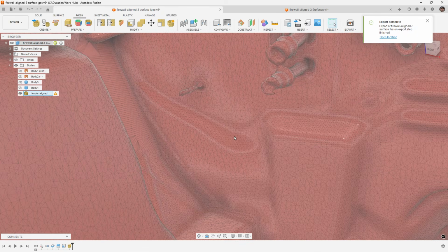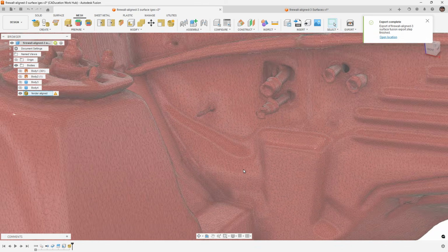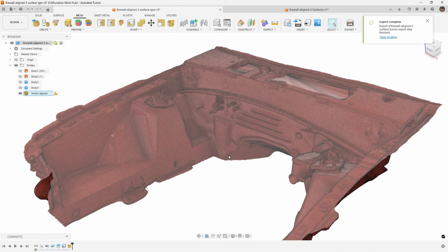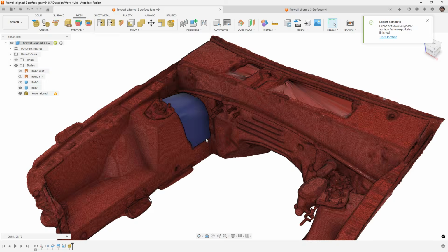So the higher quality that you can get in those areas, the better off you will be getting your parts to fit. So if you're going to scan an entire engine bay in this case, you might do a secondary scan at higher resolution and do some additional processing in just that area and align them, and then use that as your final to work on getting a cover like this to fit. That would be a suggestion for you.